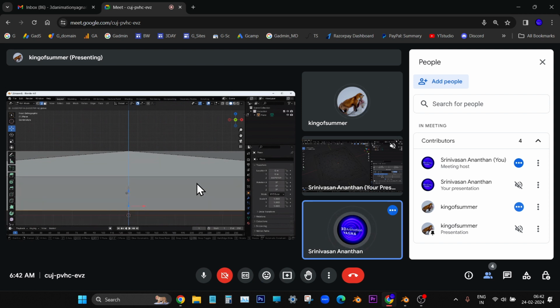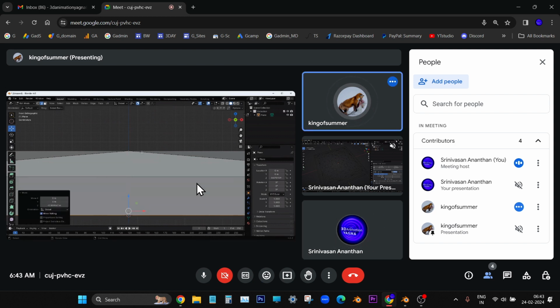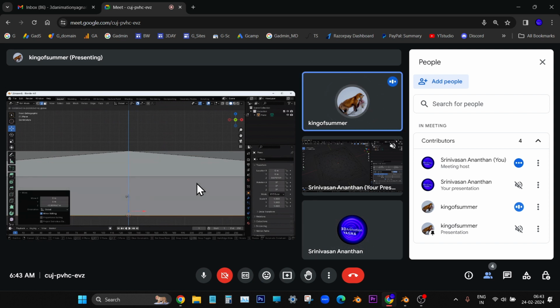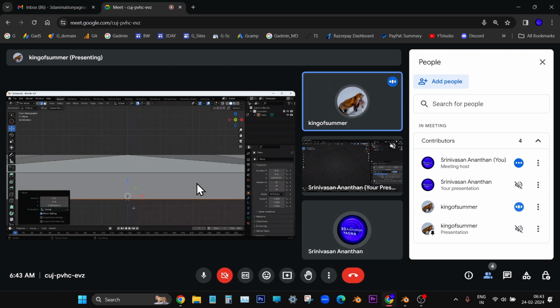It's not snapping. I think you go to absolute, check whether it is on. Are you pressing Control? No? Once you switch on the horseshoe, you need not press Control actually. Once horseshoe is switched on, we need not press Control, because both are the same options. Right.